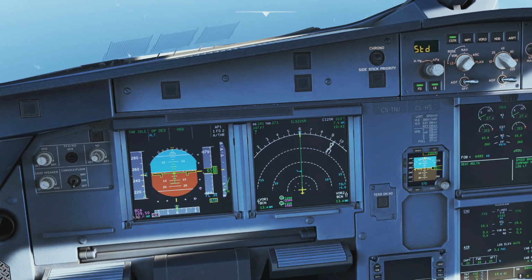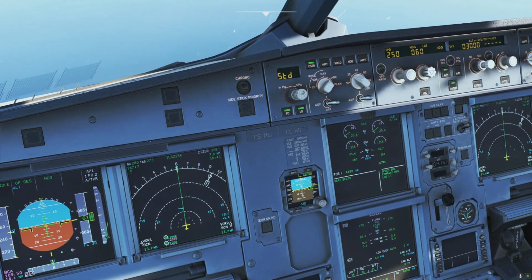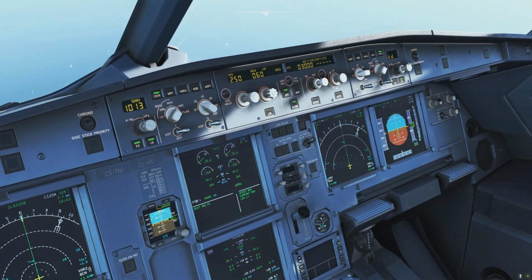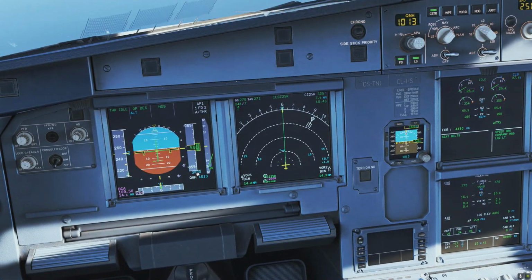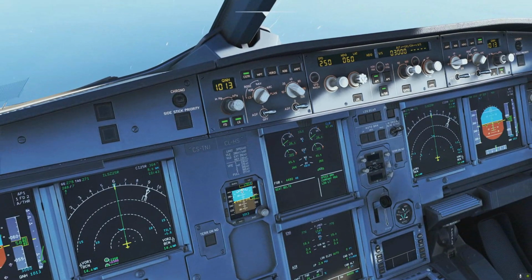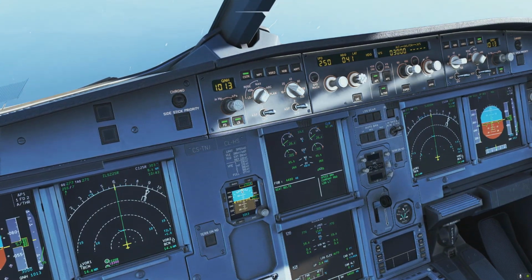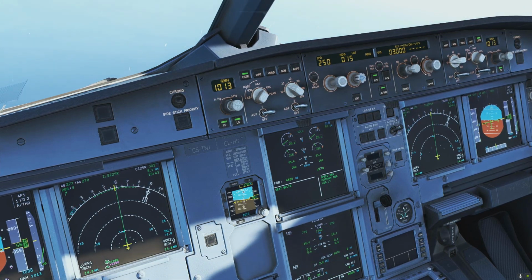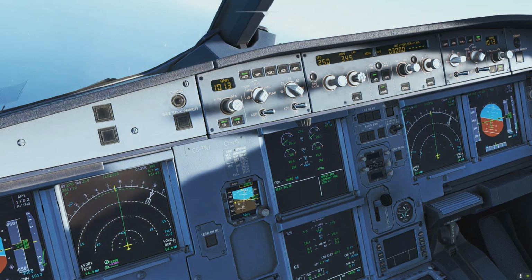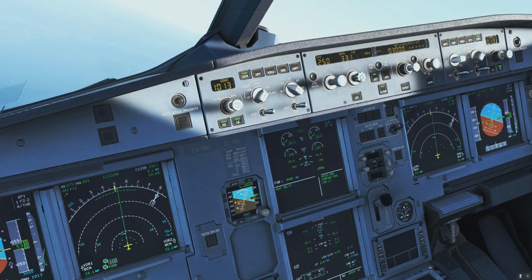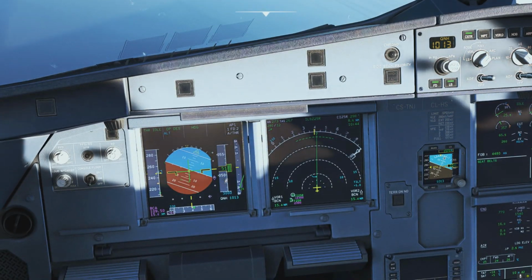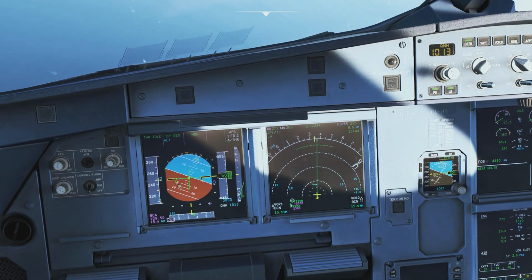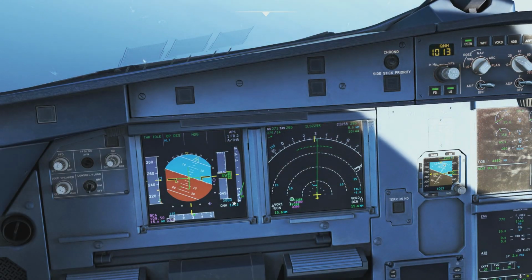We are 13 miles away from the ILS. We're at 6,000 feet. We're just passing the transition altitude here to switch over, so we'll do that quickly. And yeah, we are going down to 3,000 feet. Now they tell us turn left, let's say heading 330 for the time being. So they are already turning us in for the ILS. It's okay because the glide slope is coming in, but we're still pretty quick, so we need to slow down.